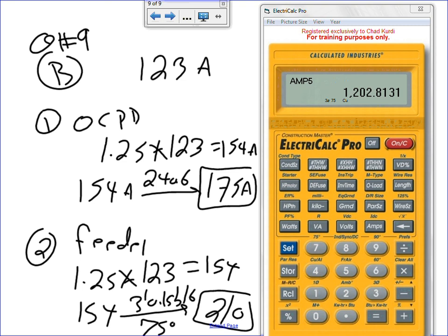Are we derating here? For temperature, ambient temperature, or for, this is a common mistake in the industry, because you don't size based on 90 unless you are derating. Even if your wires are rated, they don't make equipment rated for 90-degree lugs. You're limited to 75 lugs, no matter what, unless you go medium voltage.